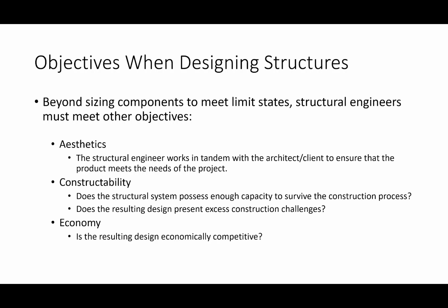Another thing that we have to consider is constructability. There are actually some limits that we are going to rigidly apply, I guess I would say. For example, we're going to be sizing and detailing bolted connections, okay? And so one of the things that we're going to have to determine is how far apart bolts can be spaced, okay? So let's say that I've got a 3/4 inch diameter bolt and a 3/4 inch diameter bolt, and